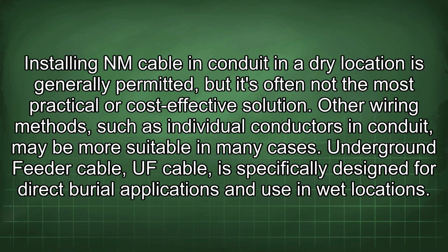Installing NM cable in conduit in a dry location is generally permitted, but it's often not the most practical or cost-effective solution. Other wiring methods, such as individual conductors in conduit, may be more suitable in many cases.